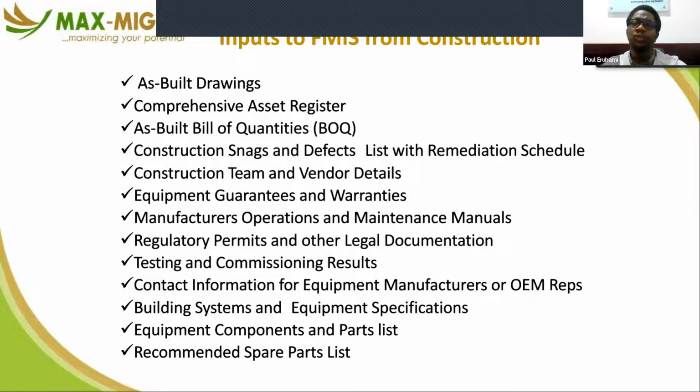But each of those materials that is used to make those floor finishing or covering has different things that you will need to work with. For example, certain chemicals will not work with them. You can't use the same kind of chemicals on granite and marble, right? Marble is like chalk if you go through the surface. And certain chemicals will just cave in and cause holes on them, whether it's deliberate or a mistake, right?